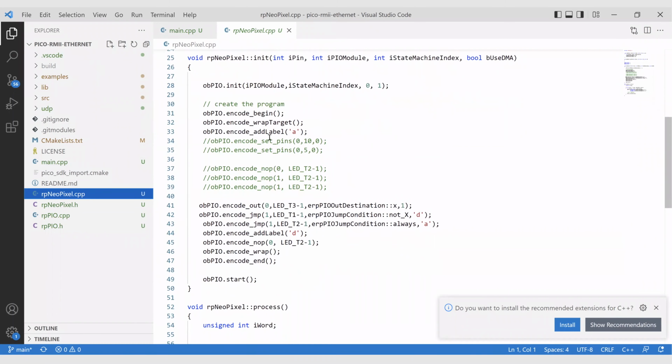But now, if you use the PIO the standard way with the SDK, you're going to actually use a PIO assembler. So they have an assembler, where you write the instructions for PIO in a separate text file, and then you compile it along with your C code. And it's actually very interesting how they do it, where you can provide the API in the same file in C. So they did a really nice job with that.